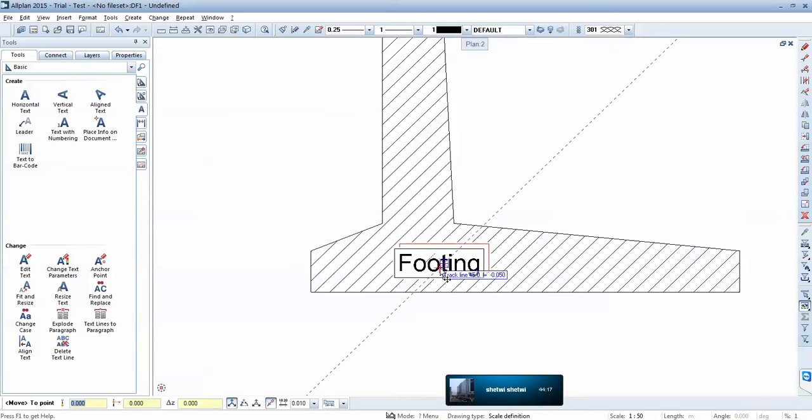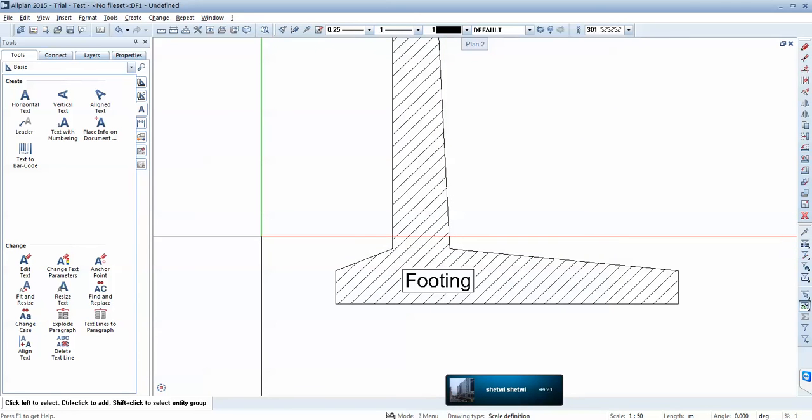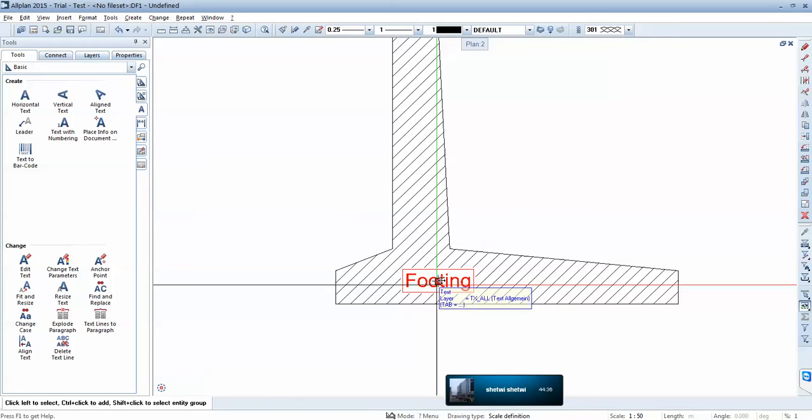So this will be a really great advantage, and you'll see further on that it's greater than AutoCAD, because in AutoCAD the dimension of the text depends on the drawing unit. However, here the text depends only on the way you want it printed on the paper. So it will automatically adjust to this scaling.